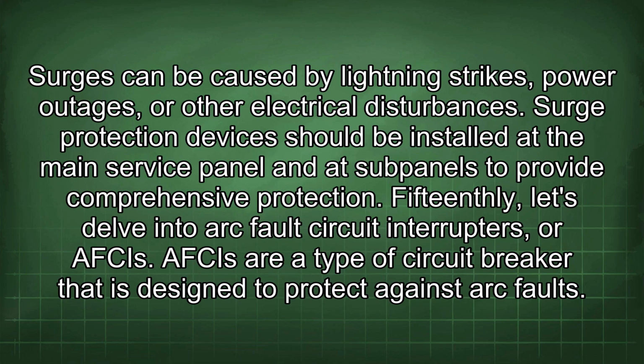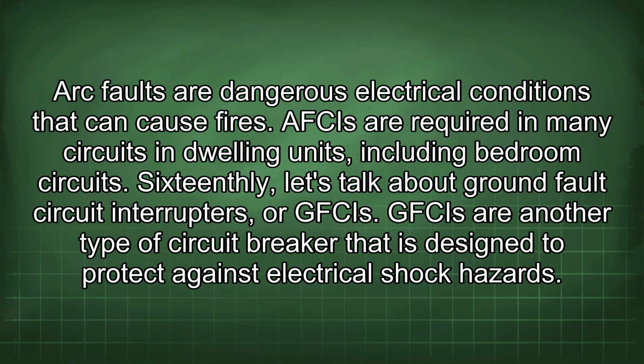15thly, let's delve into arc fault circuit interrupters, or AFCIs. AFCIs are a type of circuit breaker that is designed to protect against arc faults. Arc faults are dangerous electrical conditions that can cause fires. AFCIs are required in many circuits in dwelling units, including bedroom circuits.